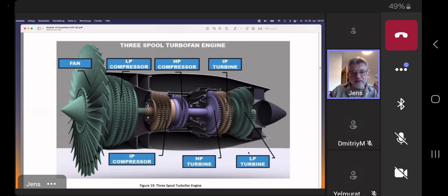Rolls-Royce especially made the decision to build those three spool or three shaft engines, which is an advantage, because in theory every compressor stage should get its own RPM in order to be in an optimum aerodynamic range of RPM. But of course this is not possible, because then you have a lot of bearing compartments. So a three shaft system, or N3 shaft system, is the maximum the industry did achieve.